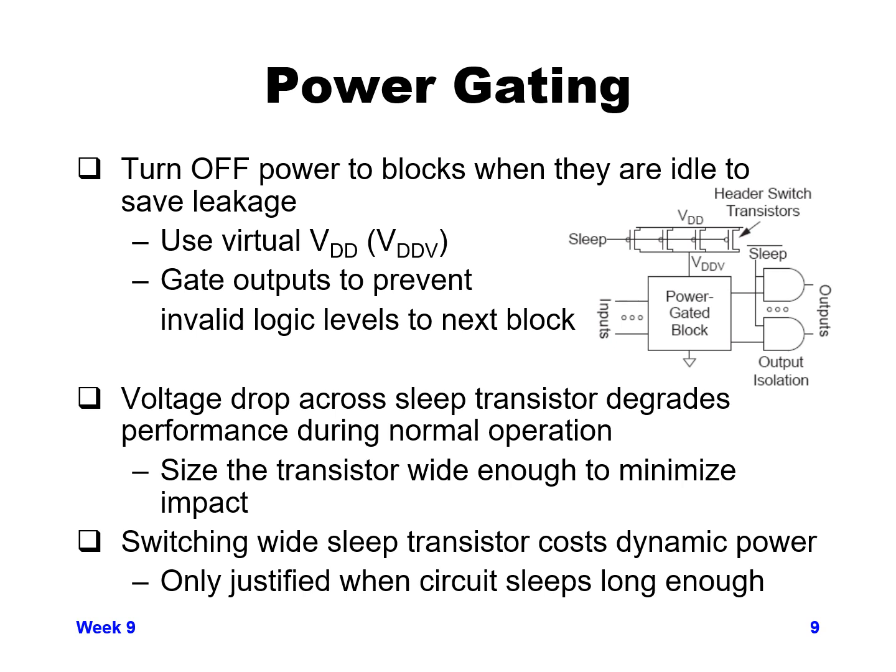And then, of course, if you need to turn your sleep transistors on or off, because you have so many of these sleep transistors in parallel, that's a lot of capacitance. So keep in mind, you don't want to turn it on and off on a cycle by cycle basis.